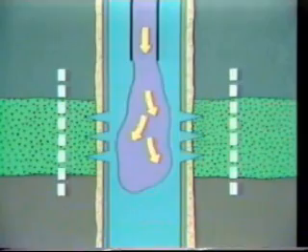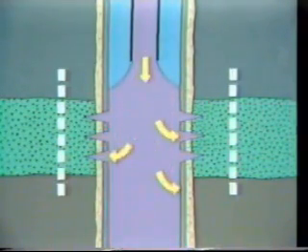Sand consolidation techniques are best applied to shorter completion intervals, where precise placement of the epoxy resin is possible. The plastic-like material is generally displaced into the formation and allowed to harden, binding the formation sand grains together. If the plastic is pumped too far into the reservoir, or if it isn't distributed over the entire interval, sand production will continue. On the other hand, if the plastic is under-displaced and left to harden inside the tubing, the well may not produce at all.